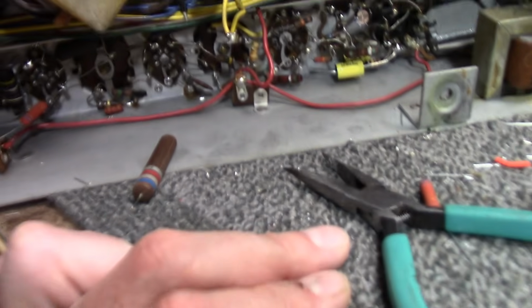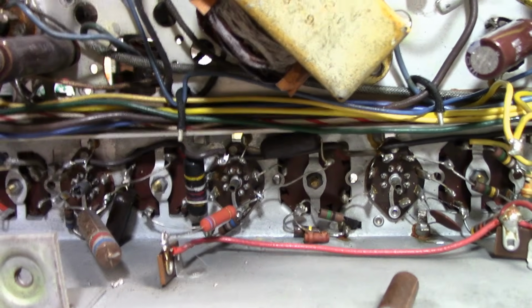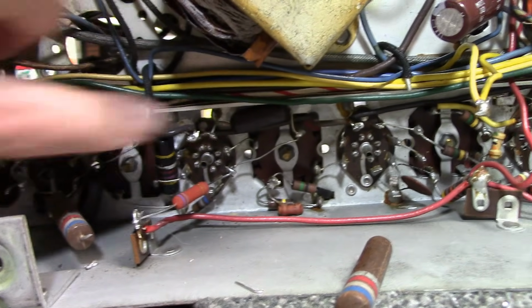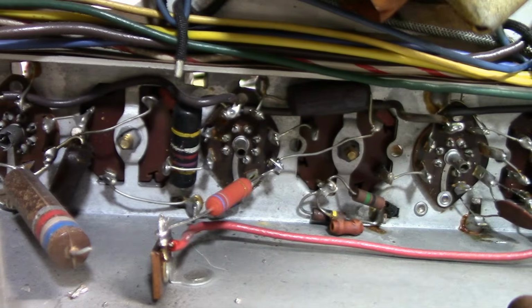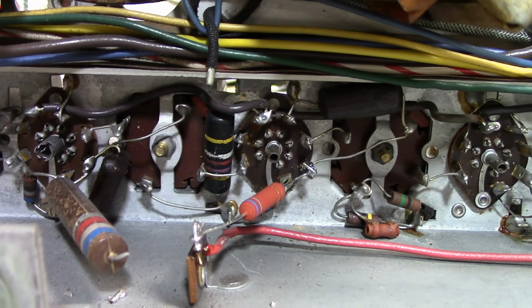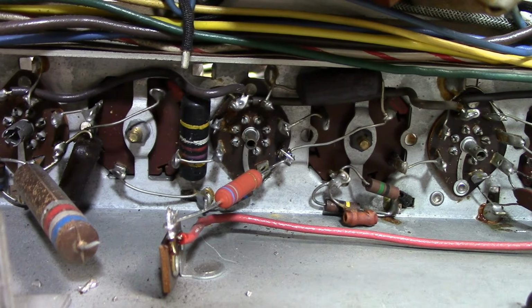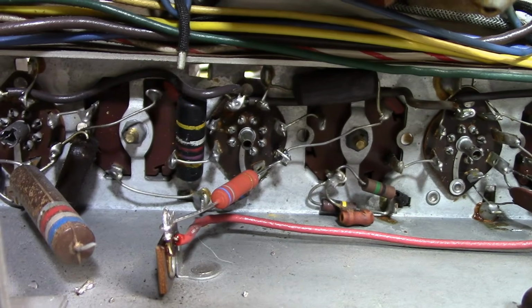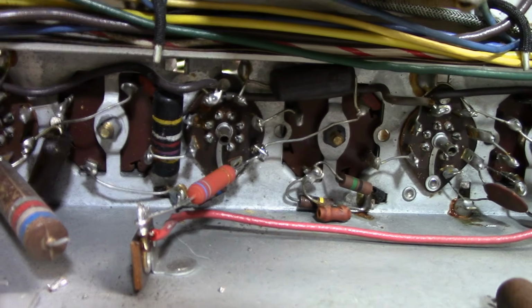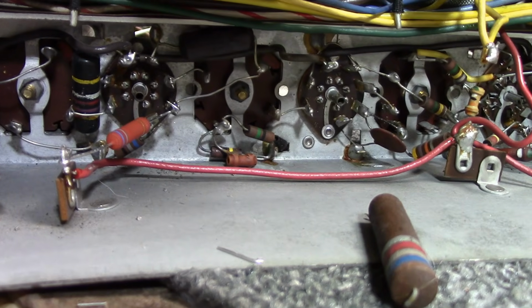While reviewing it, I realized something. One, I missed one bumblebee cap, but also that guy and that guy, they look like mica caps, right? Pretty darn sure they're not. What they are is 0.0012 microfarad caps. For whatever reason, Zenith, for the first few years of these porthole sets, always used kind of an oddball value in the sound circuit. But what I'm used to seeing is them being in bumblebee format. These are not, but I'm pretty sure they're just paper caps hiding inside of Bakelite housing.